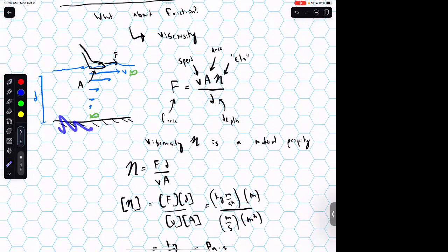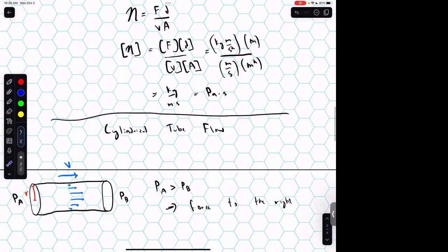And so this bottom surface affects how much resistance I feel against shear. So if I'm trying to drive a flow through a tube, effectively, the closer I am to some wall, the more friction I feel. And so the fluid near the edges tends to move a lot slower. So I can move fluid through a pipe, but it's not all moving uniformly. Really, the center is sort of moving faster.